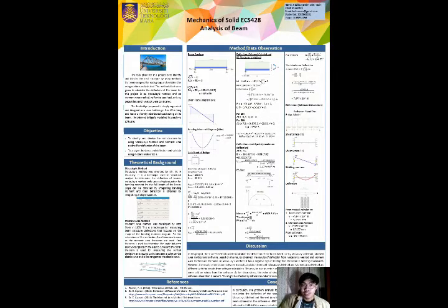I'm going to present to you about theoretical background, the beam analysis, and the geometry of the bridge. First of all, we go for Macaulay's method. The technique used in structural analysis to determine the deflection of the beams. It uses a single equation for bending moment for the full length of the beam. Slope can be obtained by integrating bending moment, and deflection can be obtained by integrating the slope equation.